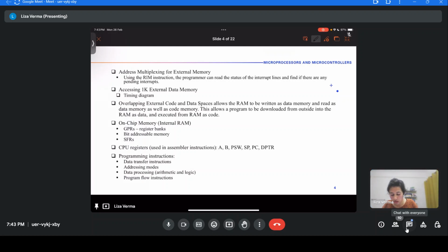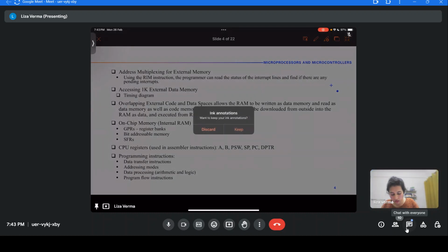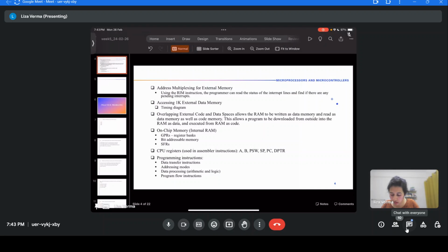Related to the stack, I have one doubt. The stack pointer being 16-bit in 8085 provided us the option of having more depth of the stack. I can initialize the stack pointer to FFFF or 0000 and use the stack from that point. Whereas if the stack pointer is 8-bit, the depth of the stack itself is limited to 256 bytes. So does it imply that in a microcontroller we don't use the stack much?